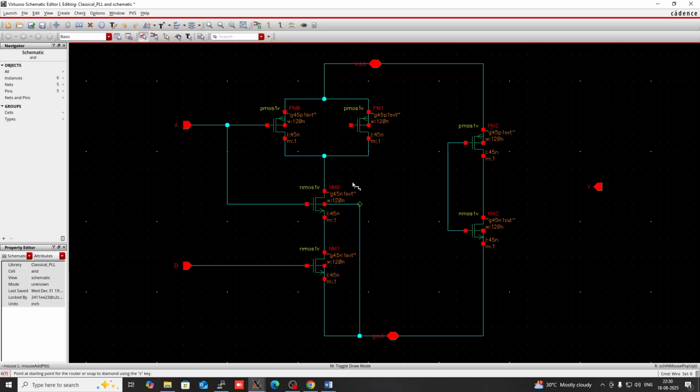Okay, actually the output of this node, this net, will be the output of the NAND gate, and I want to design an AND gate, so this is the input of an inverter. So connect this with this. Okay, so what signal you get there will be inverted by this inverter, and the output of this inverter will give you the AND operation. Okay, so press W, then connect this with this.